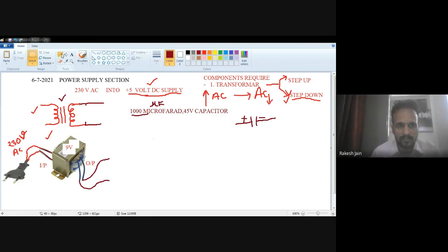And how does the bridge rectifier look? You know, the bridge rectifier symbol is this one. Two cathodes. After this bridge rectifier, you will use a capacitor. Okay. So that time, I will save the timing. Instead of explaining which terminal is plus or minus, which capacitor you require, what is electrolytic, what is non-electrolytic, apart from that, I just connect the capacitor. Okay, so you require a bridge rectifier.